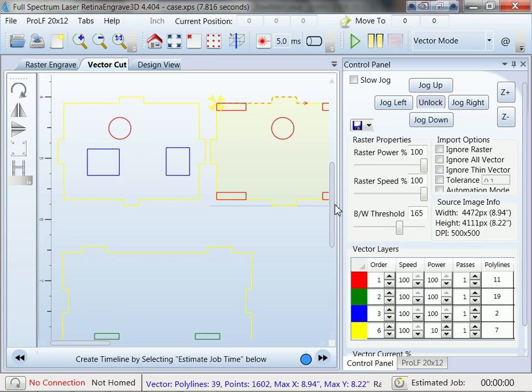So one of the nice things about that is when you outsource, they'll fabricate it properly and you'll make a lot of them, and the costs aren't too terribly high in terms of startup costs. I think the one-time startup costs are what really kill injection molded plastic, especially for products that we might take to Kickstarter, because we don't normally envision selling tens of thousands of things on Kickstarter.